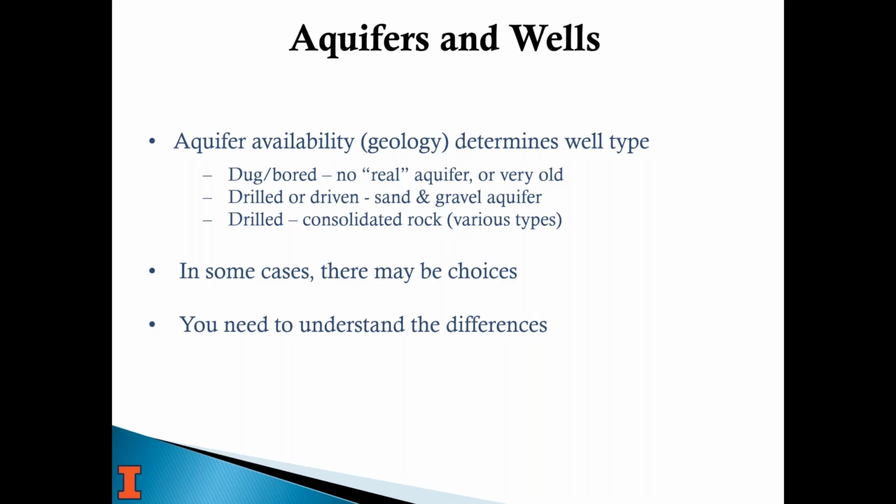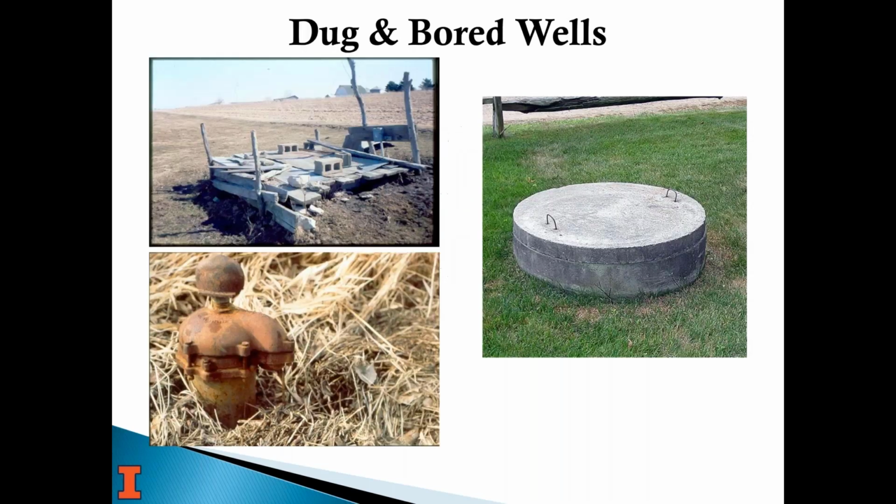Southern Illinois was part of an inland sea, and so some of the bedrock down there has plenty of water available, but the TDS is near 10,000, which is basically seawater. And so it has to be treated heavily to remove all that if you were going to use it. And so in Southern Illinois, there are many more dug wells, hand dug wells, or cisterns, or rural water districts where they're using a large lake to supply water through a whole county. So it just really depends.